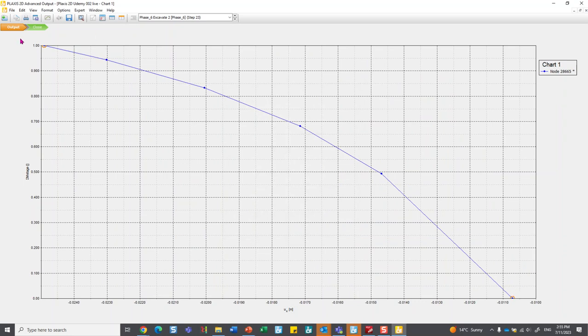So the point has moved from zero displacement for each phase here. This is sigma m stage. It means at 10% of the excavation, 20% of the excavation, 100% of the excavation. You see the point really moves gradually more into the excavation to reach a value here of close to, you can basically get this value here, it's 25 millimeter, as you can see.